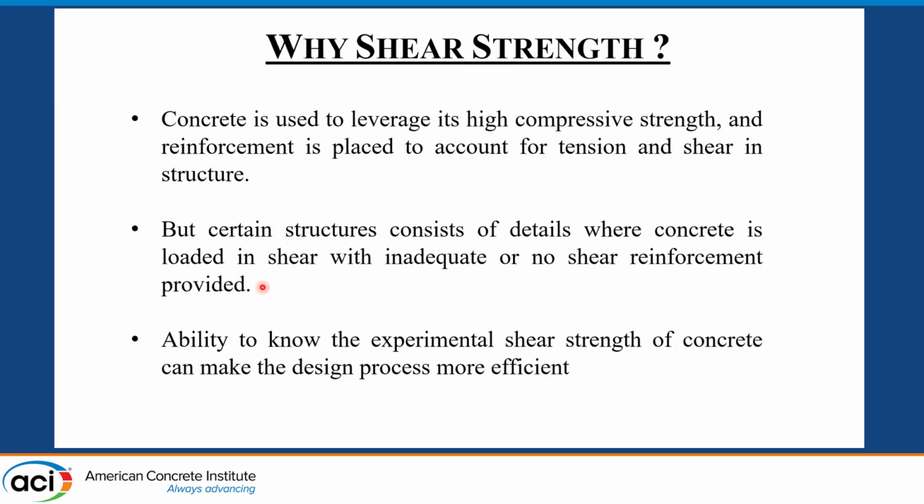So that's one of the main reasons why we wanted to know what the exact strength of concrete is under shear. We already have several prediction models to predict the shear strength of concrete based on compressive strength, but we don't have an experimental methodology, just like we have the split tensile test for tensile strength of concrete or concrete cylinders for compressive strength.